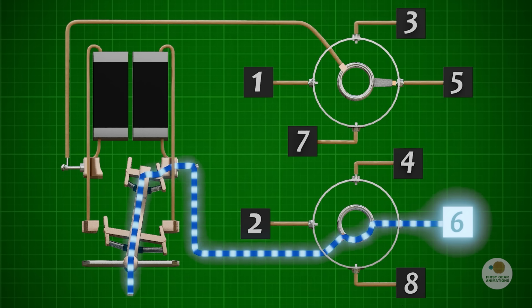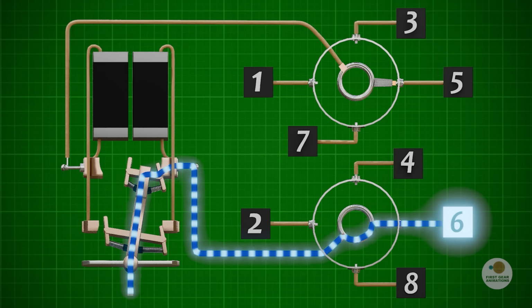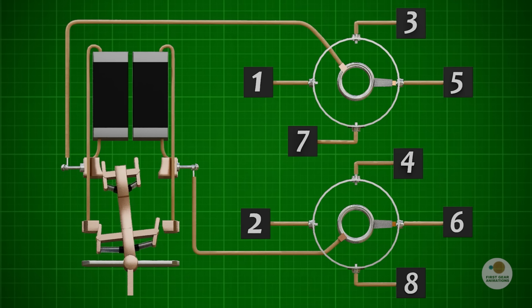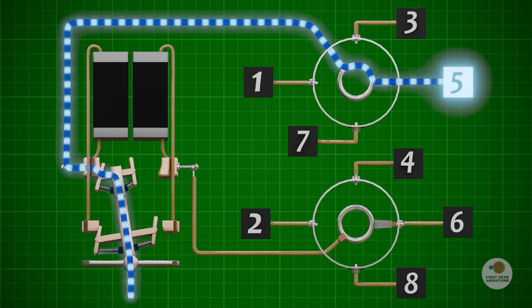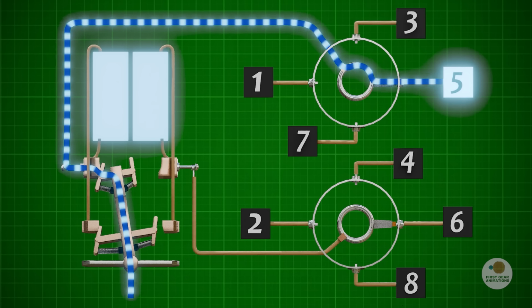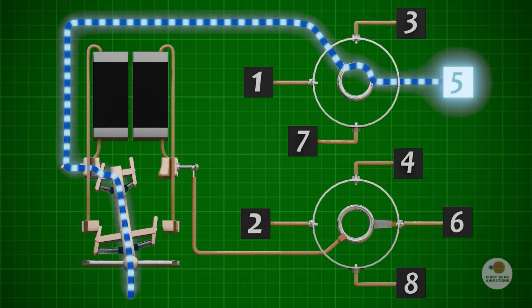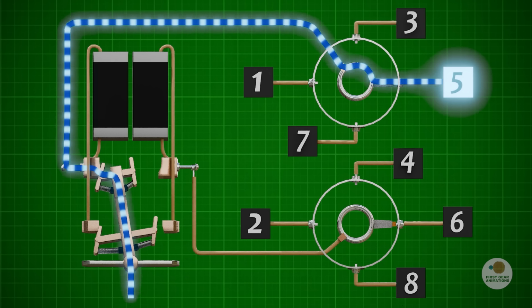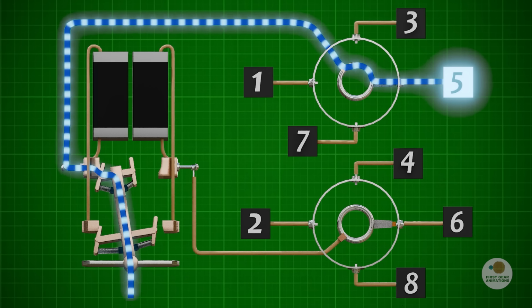Since it is not carrying any current yet, the movement creates no arcing. Once the next tap is pre-selected, the diverter switch performs a fast changeover to the odd side. This transition happens in just a few milliseconds and uses transition resistors to temporarily limit the current, ensuring the load is never interrupted. Let's slow things down a bit and watch that switch again in super slow motion.